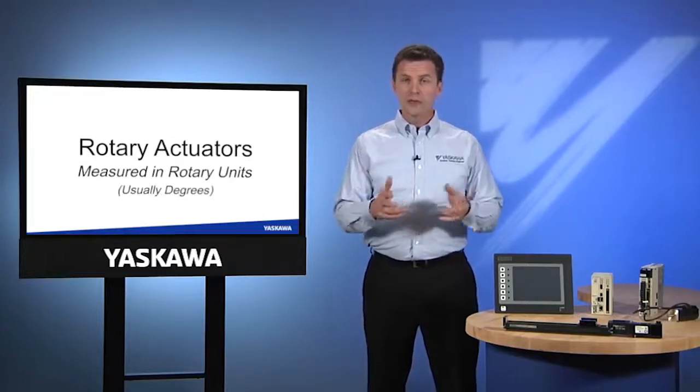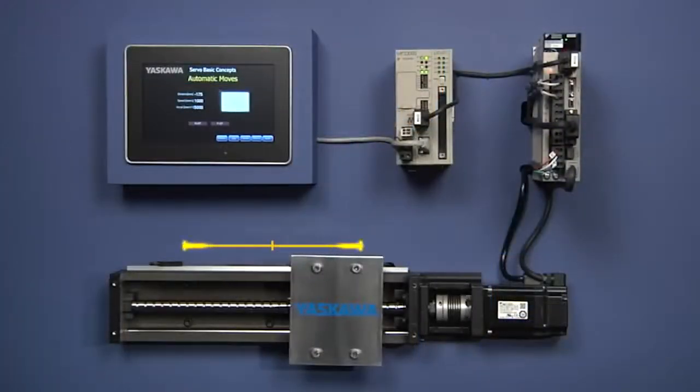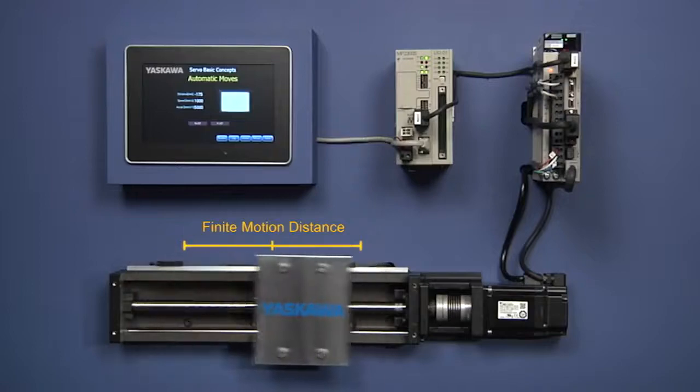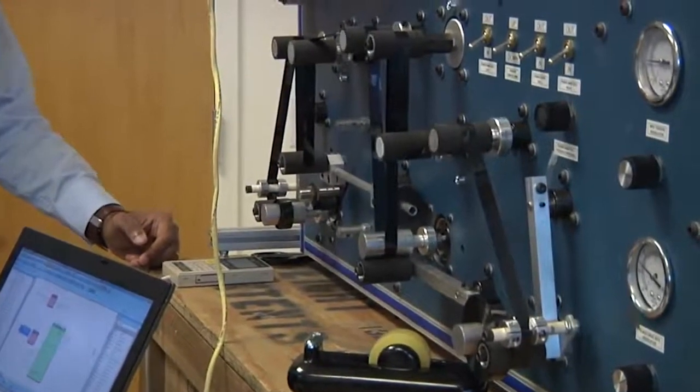Now, within these 2 categories, there are 2 subtypes, finite and infinite. For example, a linear actuator has a finite distance it can move, but a pinch roll can pull material virtually forever. A rotating fixture with cables has a fixed distance it can move without twisting or breaking the cables, but a rotary table can keep spinning endlessly in the same direction.